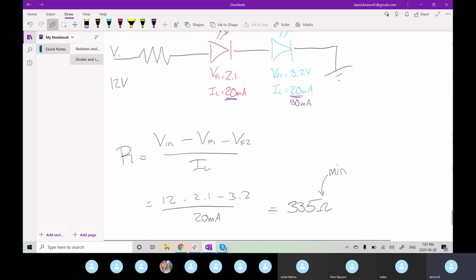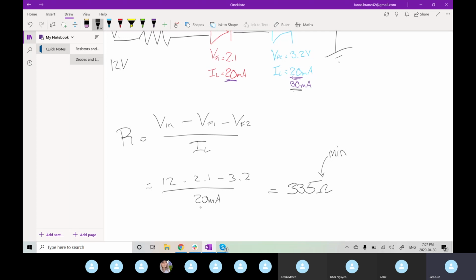And yeah, this one maybe does have a limit of 30 milliamp. You still want to run the design at 20 milliamp, just so that the overall system, since it's going to fail at 20, is designed at 20 instead of going for your upper limit.